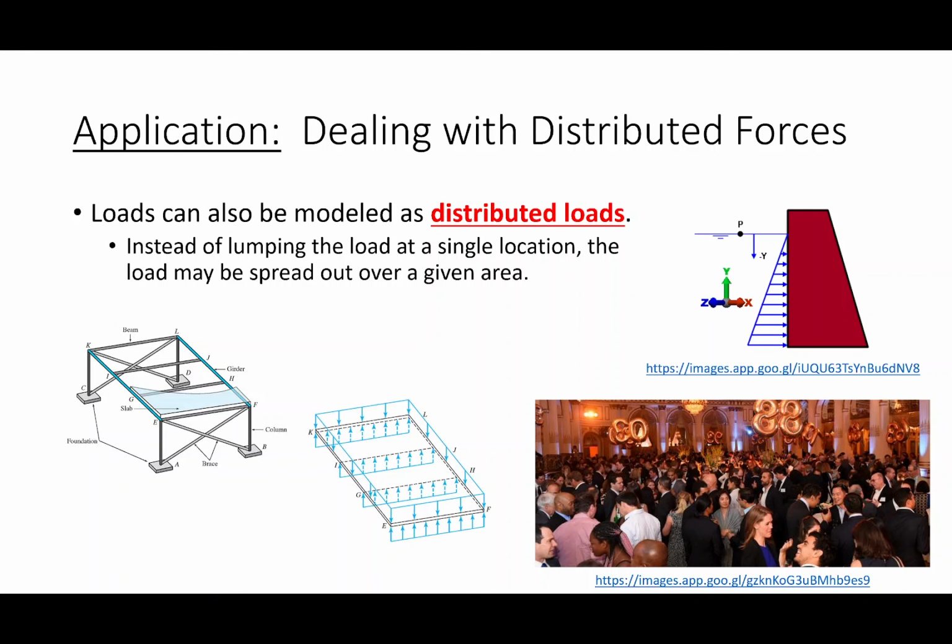A simple example, and again, I know I'm throwing a dam here, but just any hydrostatic force effect is going to be considered a distributed load. So this would be applicable to mechanical engineers, electrical engineers, civil engineers, maybe even you biomedicals. As you are in water, okay, the deeper that you get, the higher the pressure increases, right? Pressure increases as a function of depth, and it's a linear relationship, right?